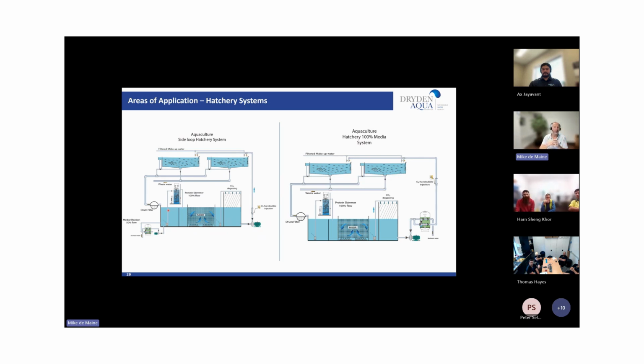Because I can tell you in salmon farms in Scotland, the organic load is so soft there, it very easily gets squeezed through the mesh. So they've got their drum filters needing to pretty much be washing down continuously to prevent that from happening, but even still, they get some penetration.